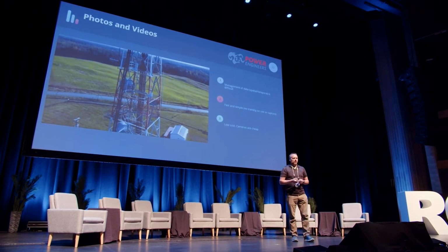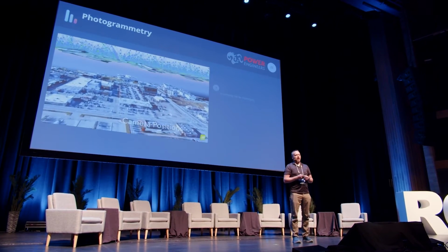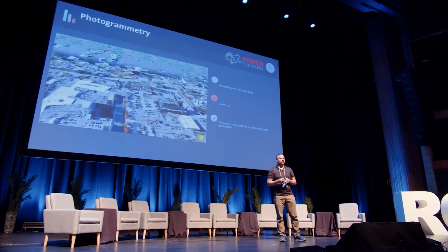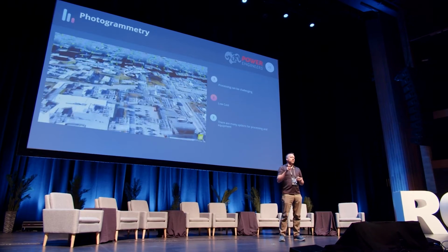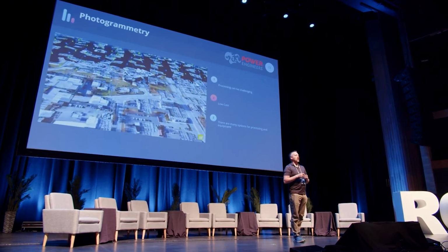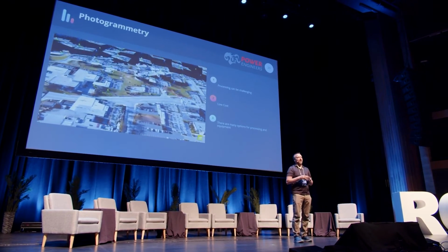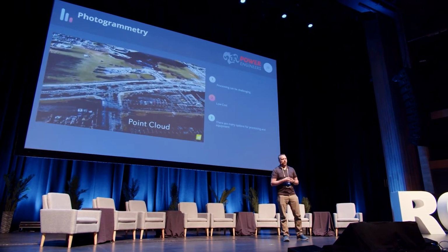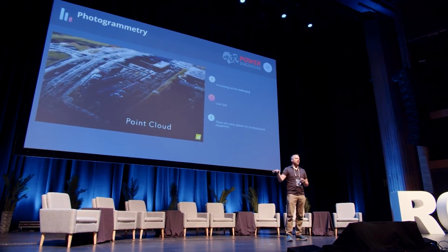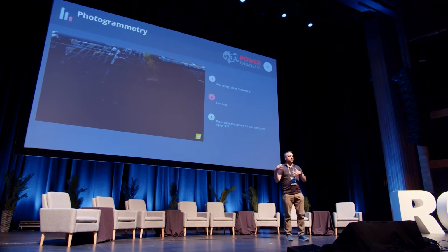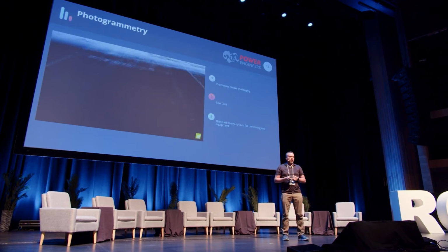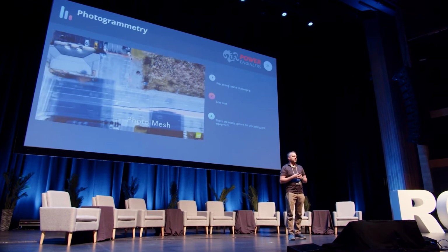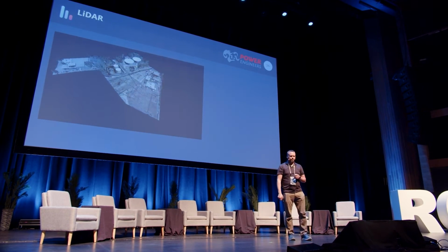Photos and videos have the other component of photogrammetry. Photogrammetry is a lot different. You've seen some slides now about using drones for photogrammetry. So this method, though, has a lot more technical requirements. Your photo overlap, your flight patterns, your camera resolutions, all those determine the quality of the end product you get. You may have grid patterns for orthophotography, or maybe helical patterns to do 3D modeling of towers and different structures. So photogrammetry is an important element, but it takes a higher level of technical skill than traditional photos and videos.